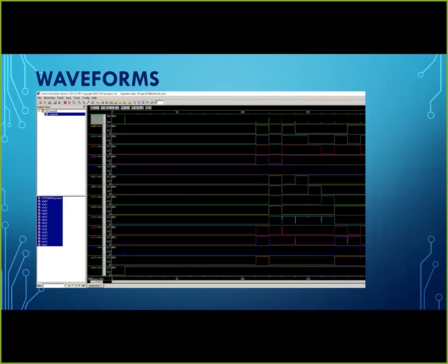This is a simulation result for the design 5 and design 6. And over here we have the inputs for the adder like A and B and the carry in, and the output is carry out. And from the simulation we can get that whatever the design we gave to the H5, it gave the correct result even after the delay, whatever the delay is. Even if we minimize the delay or area is moved, we get the correct result. So for every design we do simulation, and this was the best design, that's 5 and 6.